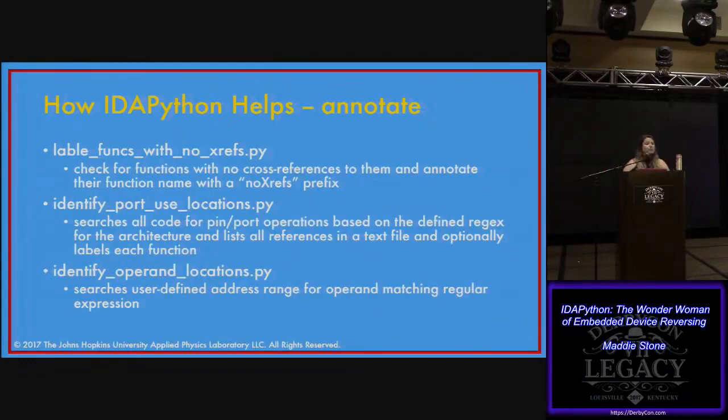The next one really gets into what we talked about, that we really just care a lot about how they're controlling and sensing GPIOs. So it uses regular expressions for each architecture for how IDA displays those special function registers or ports whenever they're interacting with them. It searches for those in function codes in your instructions.